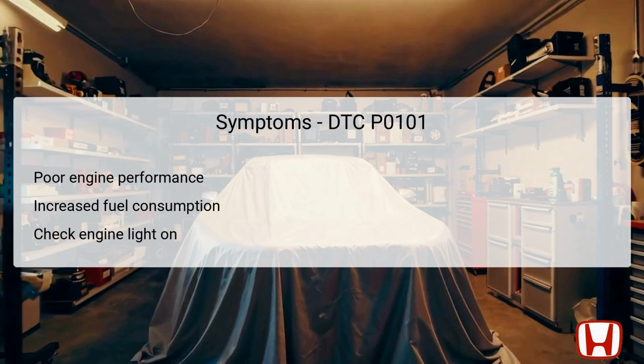The vehicle's check engine light will typically illuminate, alerting the driver to check for diagnostic trouble codes. Additionally, it might exhibit rough idling or stalling during low-speed driving. Recognizing these symptoms early can help prevent further damage to the engine and maintain vehicle efficiency.